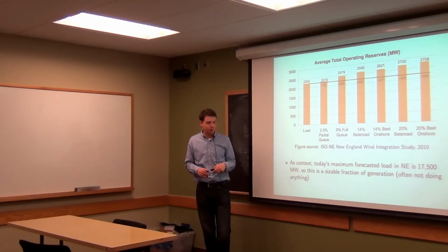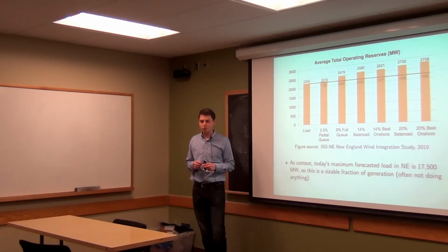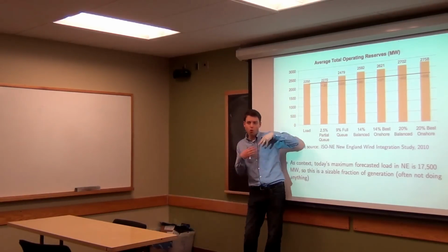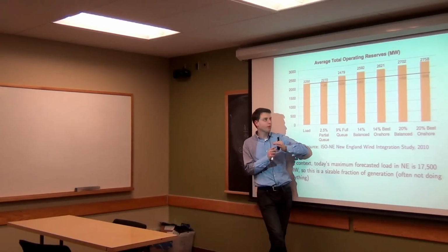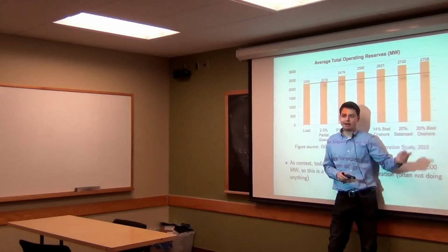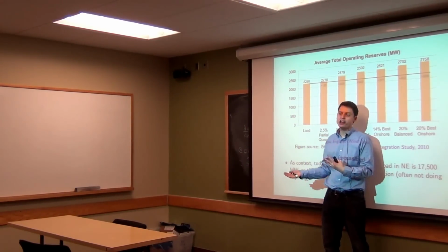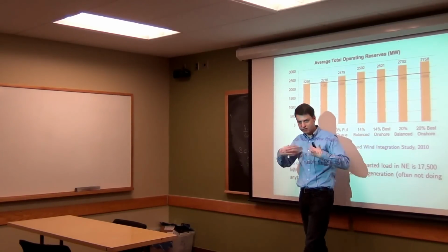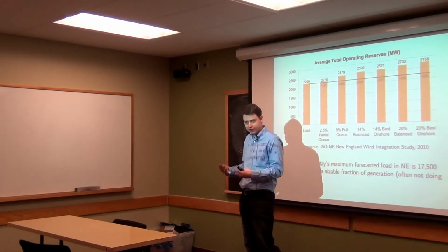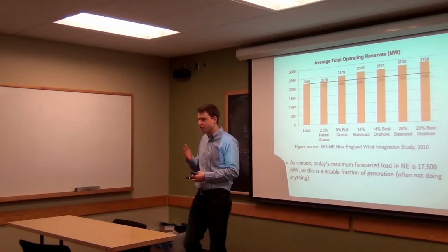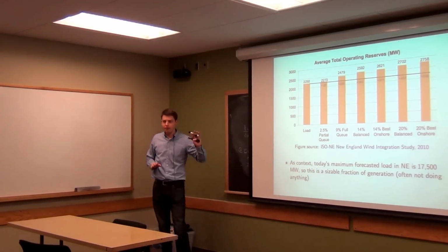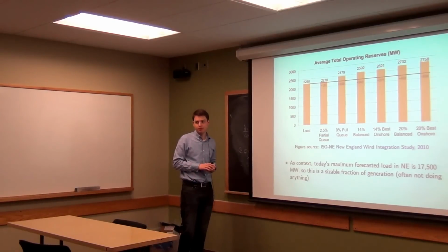The other really important question, of course, is how can we do better? If we know what was going to happen with the wind, we could probably do a lot better than this, right? Because we wouldn't have to have things that could respond quite as fast. We could make better plans ahead: the wind's going to drop down in 20 minutes, so get some things that may take longer to speed up, get them going now. So predictions really factor in very heavily to these numbers.